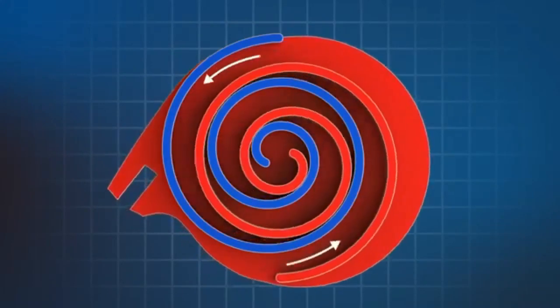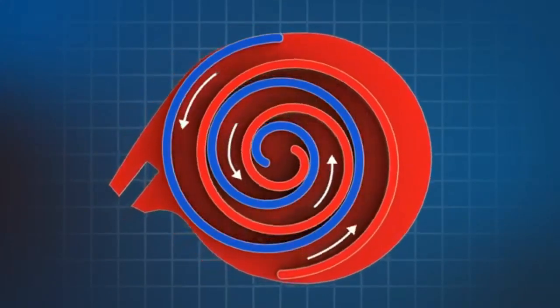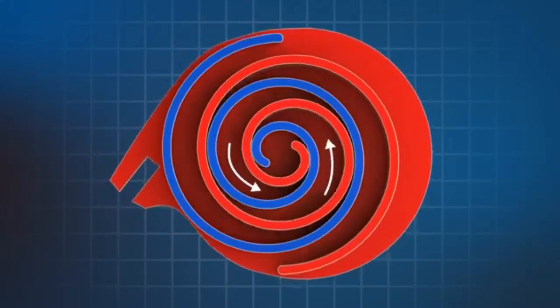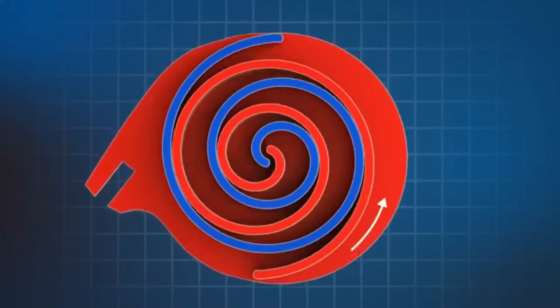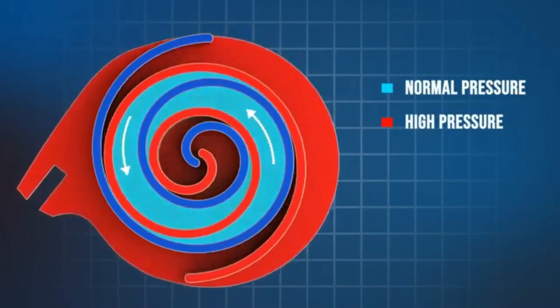The gas is absorbed in the forming chambers, and transported to the center of the scroll set. As the rotation progresses, the chambers become much smaller, so that the gas is compressed within the compressor. Therefore, this type of compression is called internal compression.